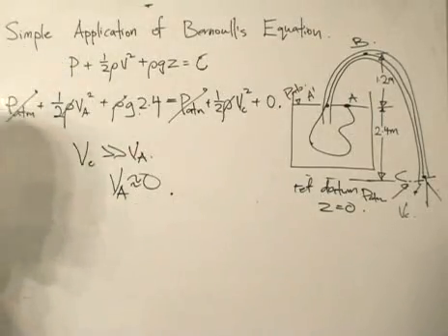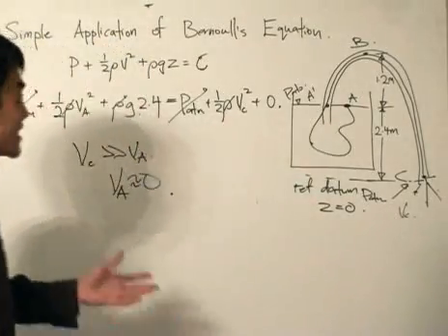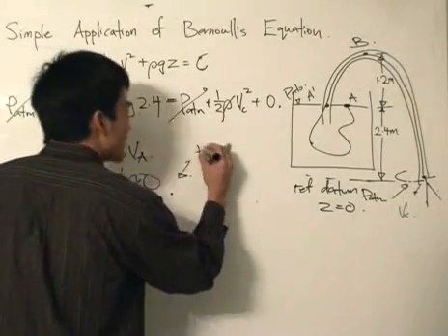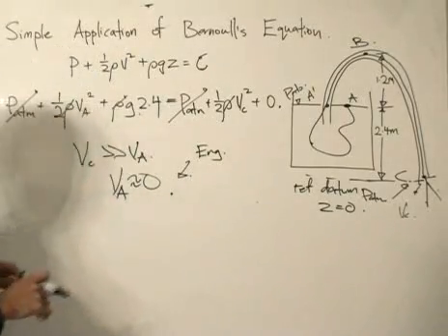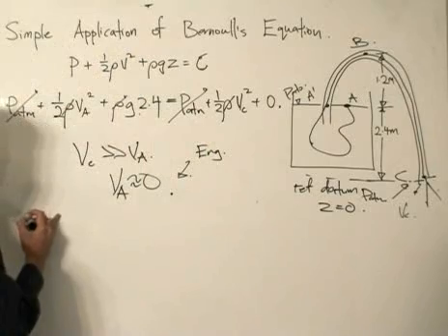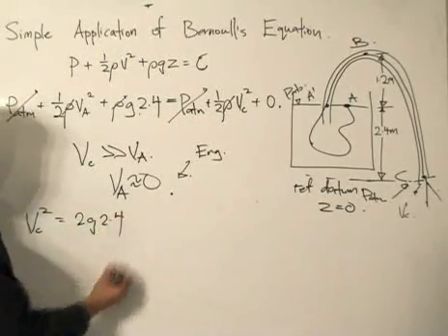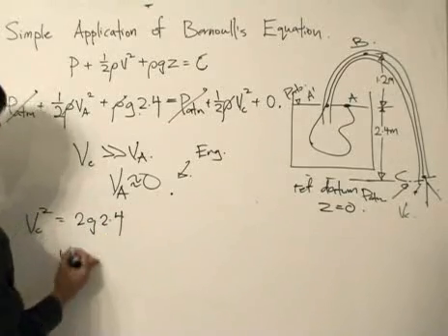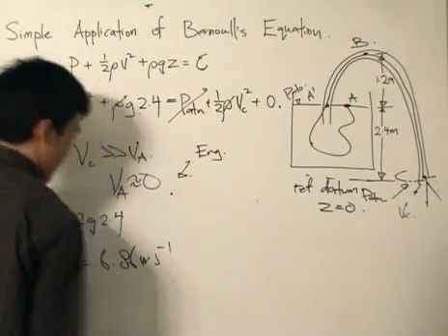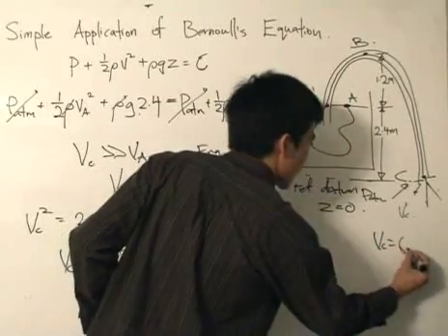Now, if you siphon some water, you don't see water at the surface moving at such a rapid pace. It doesn't. Okay, so with this assumption, and I would just like to say this is from an engineering standpoint, just take it as an engineering standpoint, this would equal 0. So basically we can cancel this out, and now our equation becomes Vc squared equals 2g times 2.4, and this Vc is now equal to 6.86 meters per second.